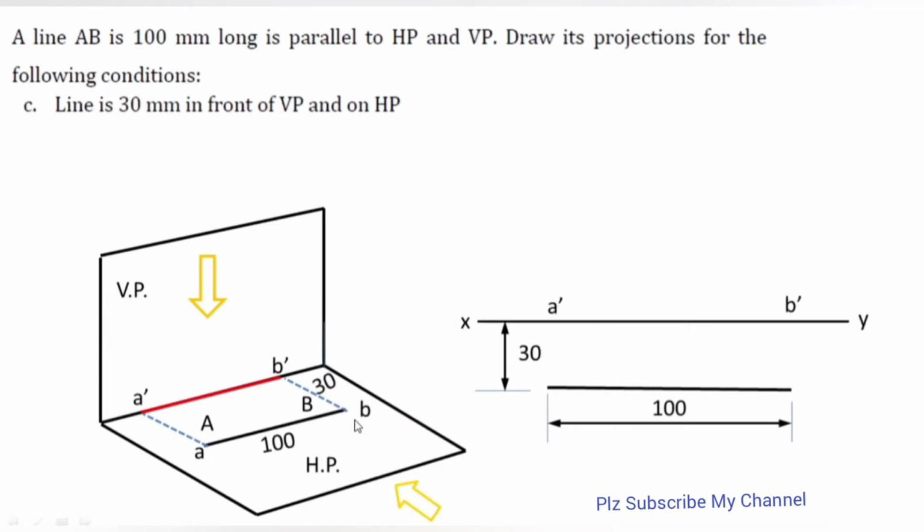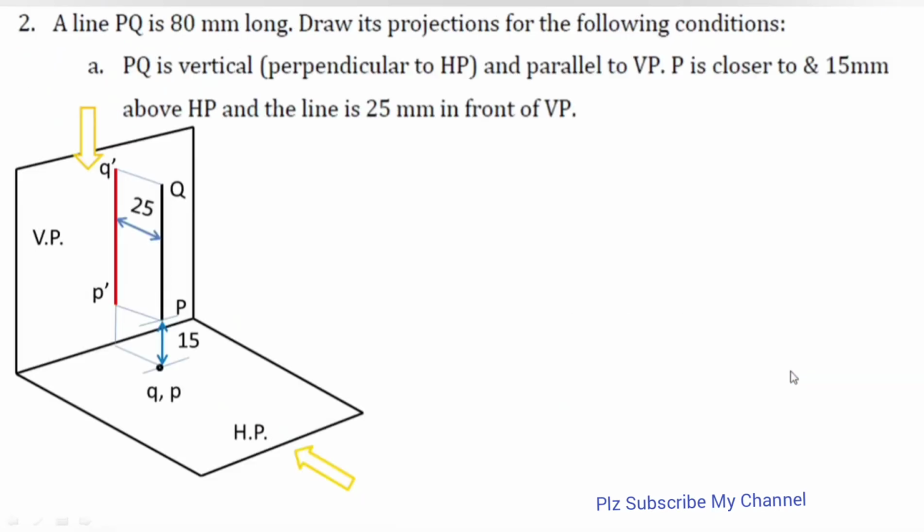And the front view is projected just above it. This is the front view projected. Its name is A dash and B dash, and small AB are the top view denotation. So we need to keep the small AB and A dash B dash dark, and also XY as dark, and this dimension line with the help of H pencil, and blue color again is denoting my projection lines, right?